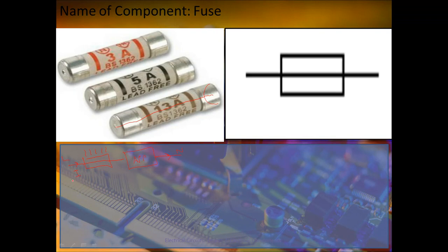However, if you had a situation where you had a power surge or too much current was flowing, or you fitted the wrong fuse that couldn't cope with the current that was flowing, that would mean that the wire inside would be thinner. That would create more collisions, which would generate more resistance and more heat. So that fuse would get a lot hotter as more current flows through it. And eventually, if the current exceeds the set level, that wire will actually melt, and that would create a gap in the circuit, which would switch the circuit off.